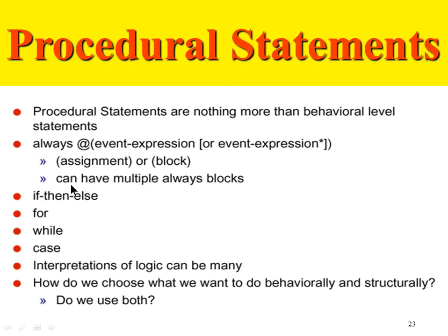And you can have multiple always blocks in a Verilog design. We can have conditional statements like if then else. Inside the always block, we can have various statements: if then else, for loops, while loops, case statements, or any other logic description. It could be a behavioral or sequential logic description. Basically, the basic building blocks of Verilog are the always block and the initial block.